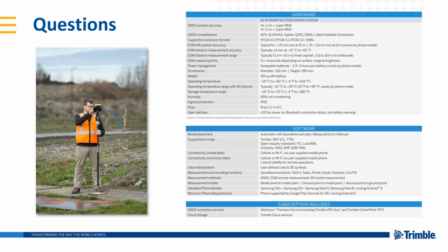Can it measure to a prism? Yes, it can measure to a prism. It would depend on your ability to point it at that prism, however, so it's not really a workflow that I would recommend. It's an EDM that's been designed to return distances off most objects in the specified range.